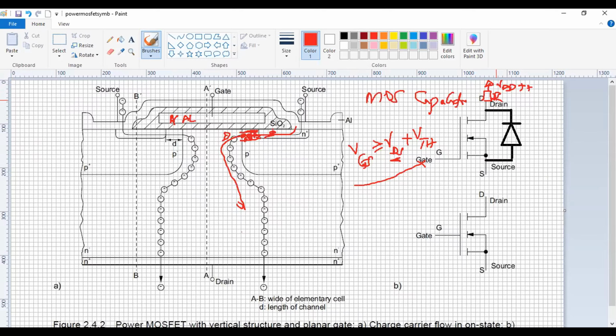The resistor acts as a load, but also controls the amount of current flowing through this device. So I'll have a drain current, ID, flowing down from VDD and ending up in the source. If electrons are flowing from source to drain, it means I've got current going the other way by convention.